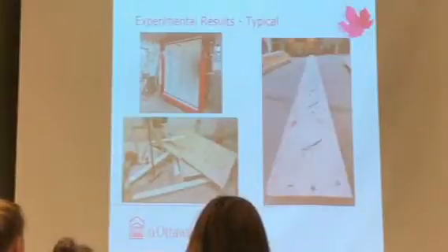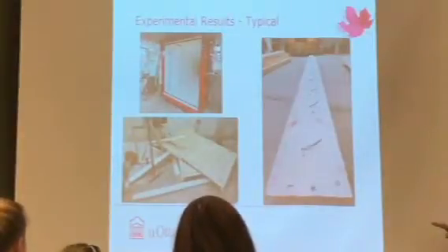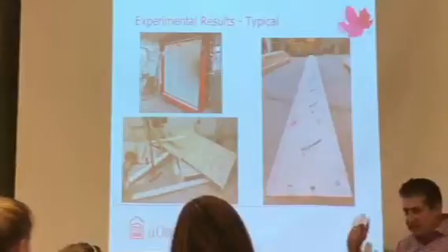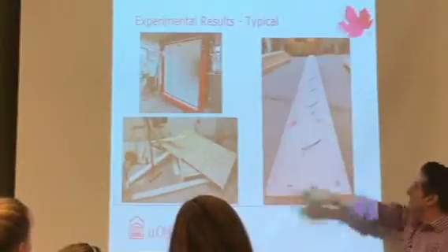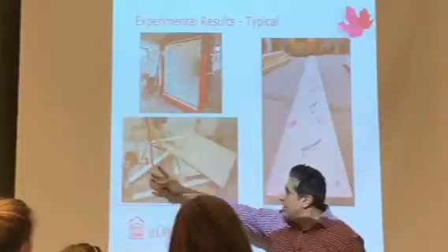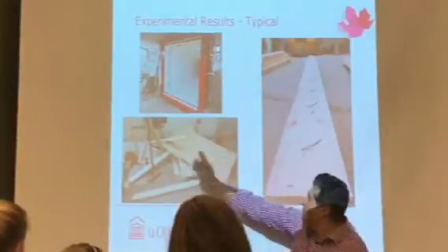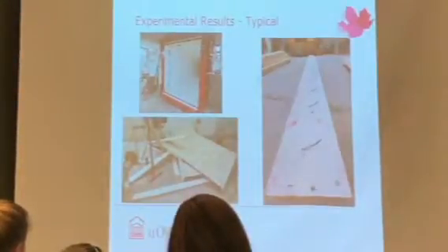How could I get those failures before? Well, I put an actual support at the end, right? I put a simply supported steel beam at the end to eliminate the effect of support. But now I want to understand actual support. How does it work? Well, I know it doesn't work. So when we talk about detailing, you see the nails, how, as the wall is moving out, the nails are just bending. You see at the end of the lab, the sheathing is there, all the studs are there. Nothing broke, right? But huge amount of debris. So essentially, this doesn't work.